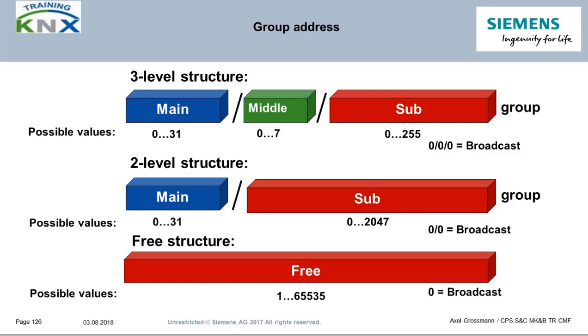As already announced, now more information about the topic group addresses. The base for it is a 16-bit large addressing field. It has the same length like the individual address, which is reasonable when you later look at the telegram structure. But as for the functionality you want to control by the group addresses, the value doesn't matter, only that the corresponding sensors and actuators are always linked to the same group address. These group addresses are thus completely free to use.